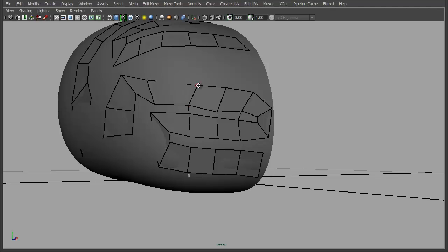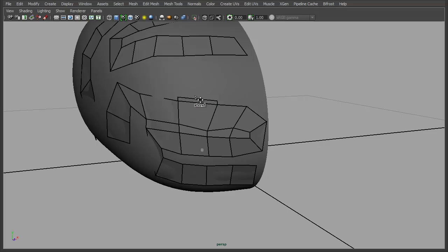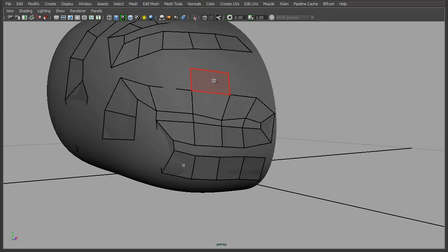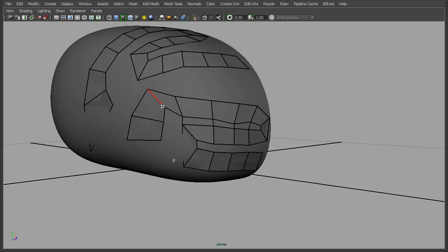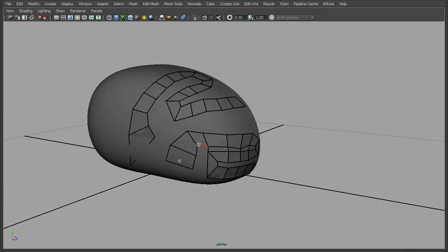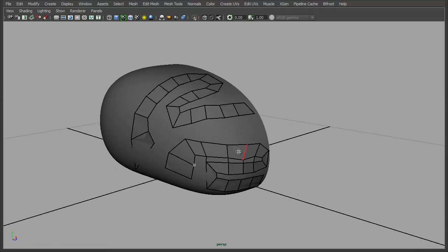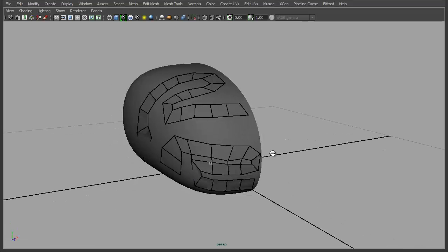Just tidy this up here, just clean it up a little. So hold down Tab, and we can extend this point to here. Just make sure those are welded, yep. And as you can see, we don't need to extend and end on a point. See, that will automatically snap, but we could just extend to there. If we don't want it, hold down Control and Shift and delete that there. So as you can see, you can very quickly get nice flows of polygons, which are going to help to start us off with dictating the main chunky areas of our brain.